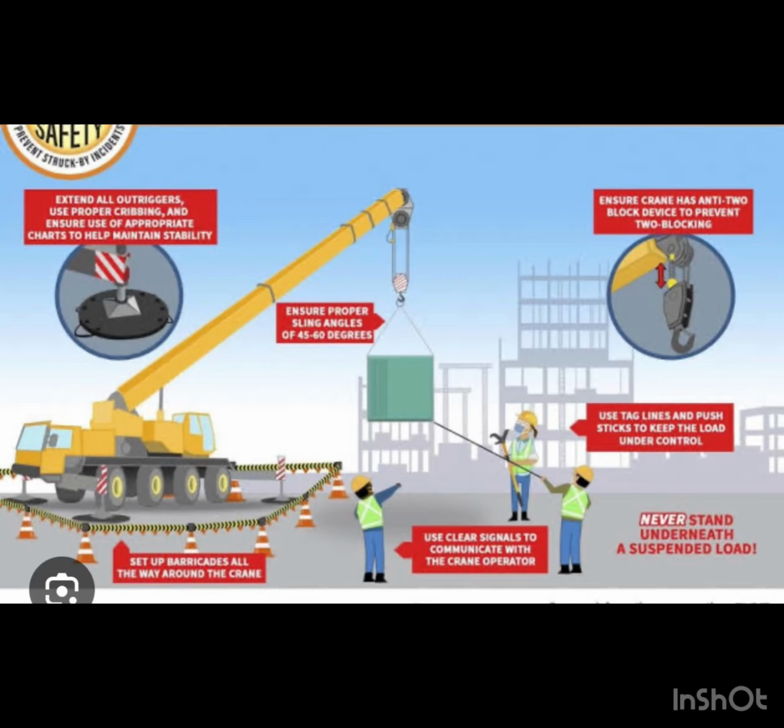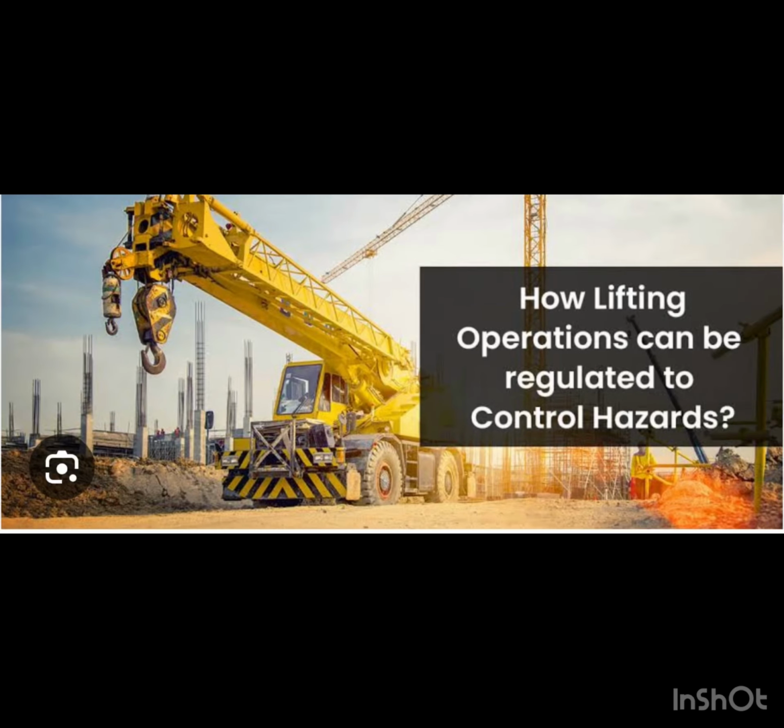What are the hazards of lifting? The hazards of lifting include, but are not limited to, suspended load, crane collapse, fall of load, damaged tools and tackles, improper signaling, uneven ground conditions, adjacent and nearby structures, overhead power lines, mechanical failure, improper rigging, uncontrolled movement of load.